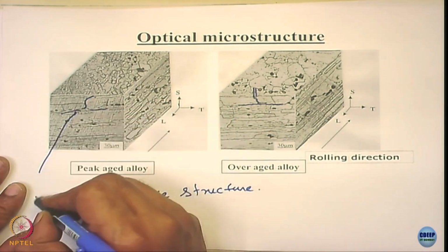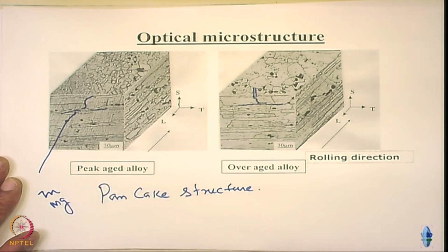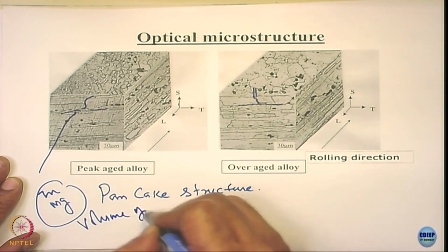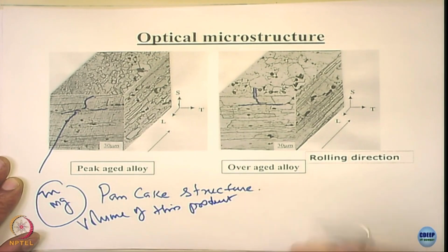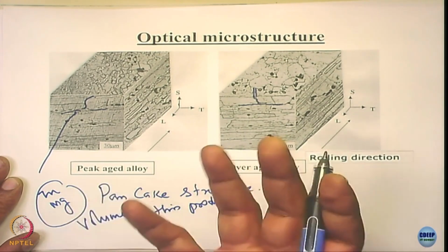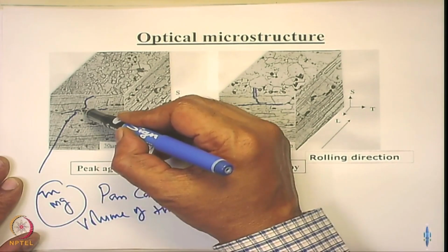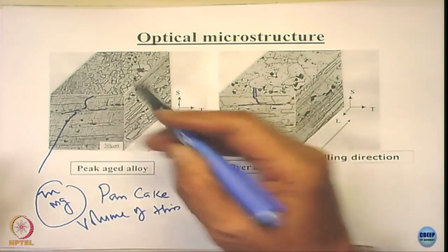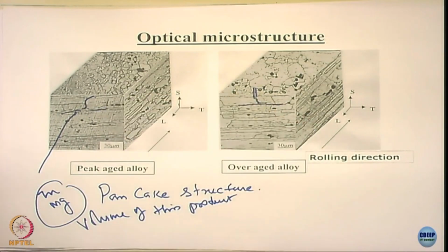it forms, let us say zinc dissolves, magnesium dissolves, what happens now? Now the volume of these products is higher than the volume of the metal dissolved, isn't it? Because it has hydroxide, all this, right? It is higher. When this volume is more, what will happen now in this case? What will happen? It is going to strain, it is going to lift the thing up. Now that means the grain starts opening. There are going to be internal stresses now.